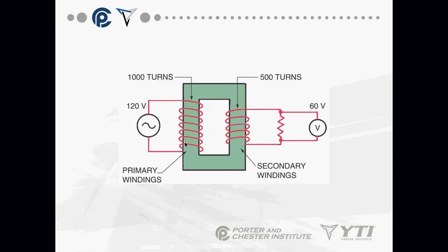By the way, look at how the voltmeter is connected. Is that in series or parallel with the load? Parallel. Okay, I know a couple people on labs got that question incorrect, and I think I made a bunch of notes on it. But the voltmeter is connected in parallel with your loads, because the load is still getting power. Your meter is getting the same power the load is getting, so it's connected in parallel. Any questions on transformers?